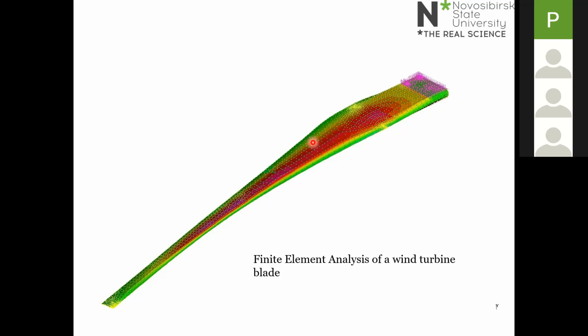If a wind turbine blade twists during operation, that changes the pitch angle of the blade. And if you change the pitch angle of the blade, you change the aerodynamics of the blade. And even very small pitch angle differences of around 1 or 2 degrees can have a major influence on the aerodynamic performance of a wind turbine blade.